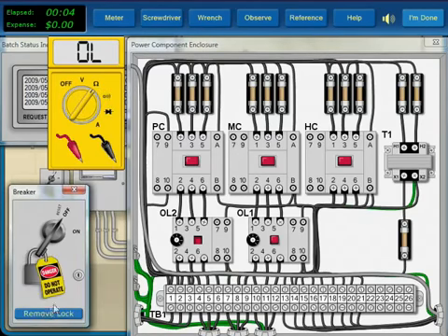So we need to lock out the circuit. Next, we sectionalize the circuit where it leaves the power box by disconnecting a wire and measuring from there to the fuse with the contactor closed. We read infinite resistance. This means that the open is within the control box.